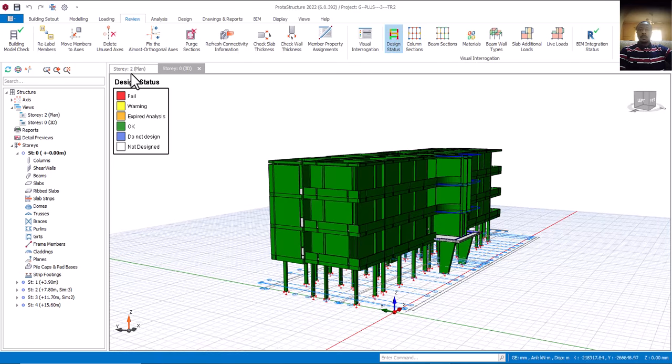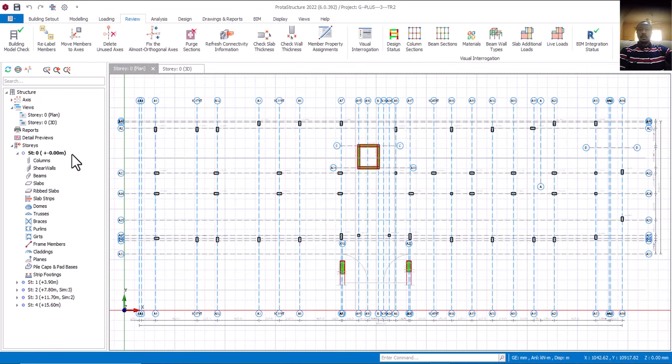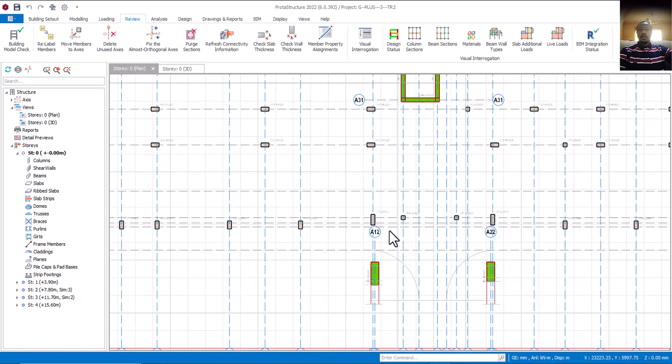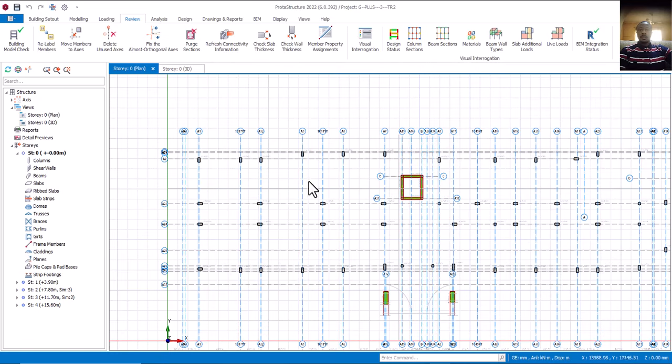So I'll come here now. Come to this place now. Foundation, story plan, and then I'll come to story 0 plan here. Double click on it to take us to the 0. So look at where we are now. Can you see it now? So this is where we are. So what we are going to do now is to begin to model our beam raft.